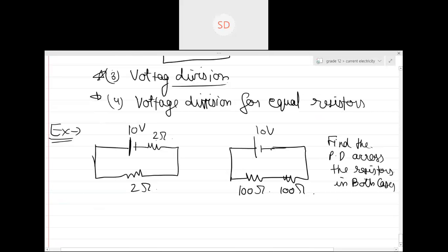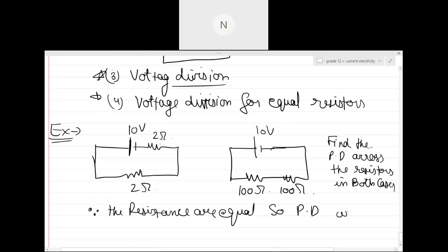And here in this case, since the resistances are equal, the potential difference will divide equally. Can you see, guys, both these 2 ohm resistors are in series? How? Can you see the current? This current, this current, the same current is entering the 2 ohm. So hence they are in series connection. Please remember this thing which I do, it's called branch manipulation, which you will be learning very soon. I'll be teaching you the SS method also.